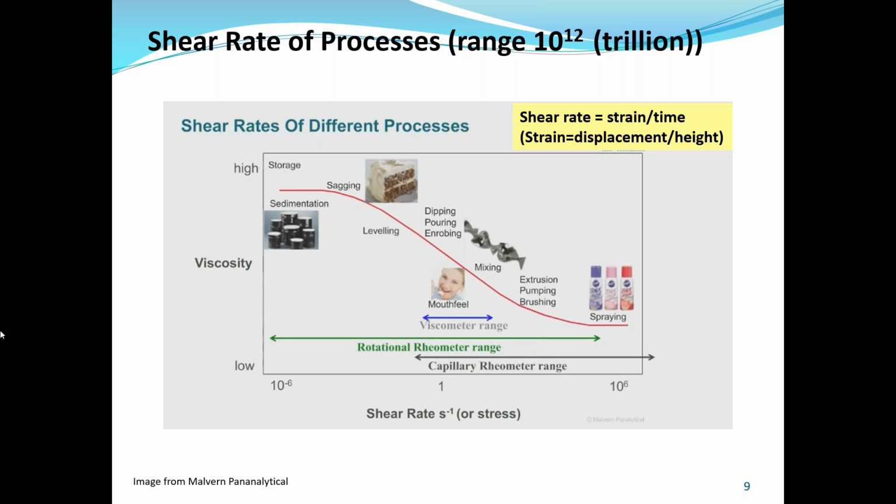that's where I was highlighting that a viscometer will give you a viscosity value given with the defined spindle type, the spindle speed, and the temperature. So if I understand the question properly, you're asking, well, how do the values from a rheometer and a viscometer correlate? Sometimes they don't, because you're really looking at different processes. You're looking at often the sample immersed in, say, the viscometer geometry is immersed in the sample, whereas the rheometer is applying a different type of force throughout the sample.